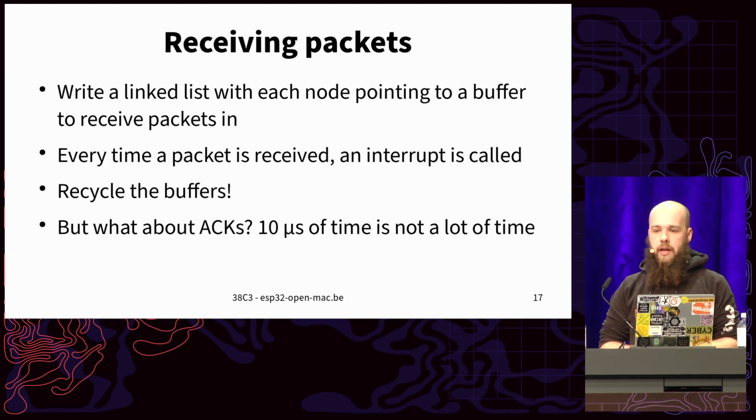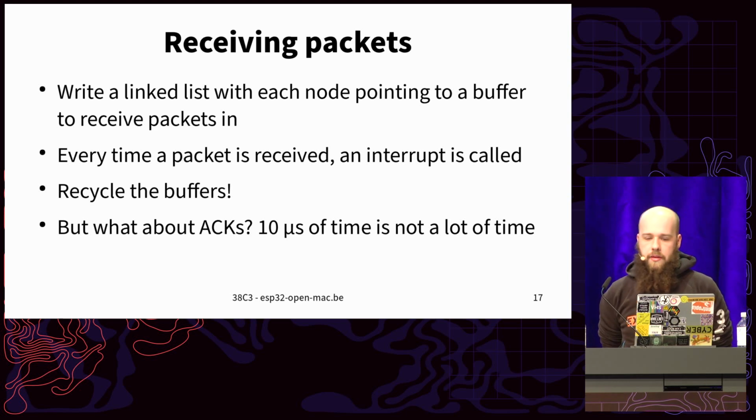And the MAC task can do it at its own tempo, because the Wi-Fi hardware will just write to the next entry in the linked list for the next packet it receives. And it's very important that after the MAC task is done processing a single packet, that it then recycles the buffer. Otherwise, if you would keep mallocing and freeing a buffer each time, it would put a lot of pressure on your memory allocator. And then another thing is that the standard mandates that if you receive a packet, you send an ACK packet back in a very narrow time frame. I think this is like 10 microseconds. So it's almost mandatory that the hardware does this instead of the software.